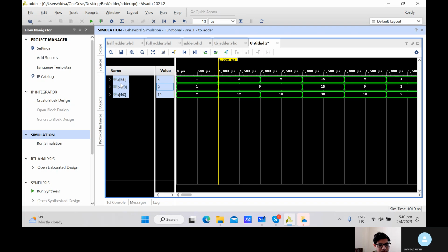Like a 2-bit comparator, a 4-bit comparator. It's simple, right? You go and design the K-map. What will be the outputs? Three outputs: greater than, less than, equal. So 3 outputs and 4 inputs. Or to simplify it, maybe go for 3-bit input only, or 2-bit input. If you want to keep it simple, let's do 2-bit. Okay, 2-bit input and 3 outputs.